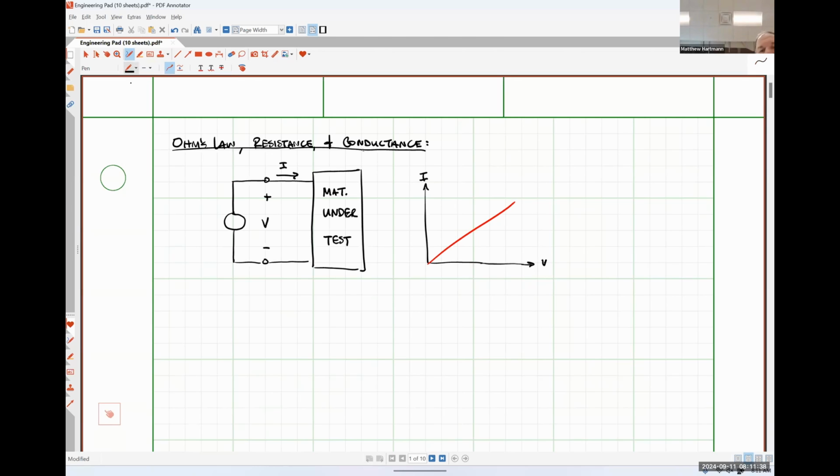Ohm's law effectively says that the ratio of the voltage to the current is known as resistance R. Now, this resistance R is actually the inverse of the slope that you guys found, because if you plot I on the vertical axis and V on the horizontal axis, you actually get a different constant of proportionality. So the ratio of I over V gives us conductance G, okay?